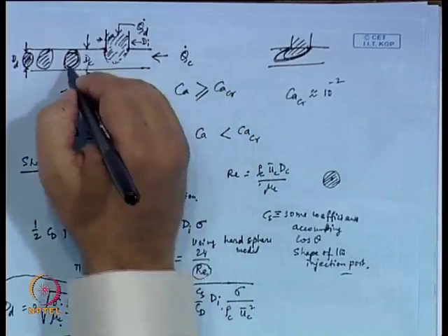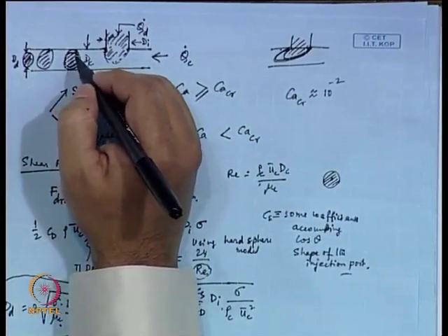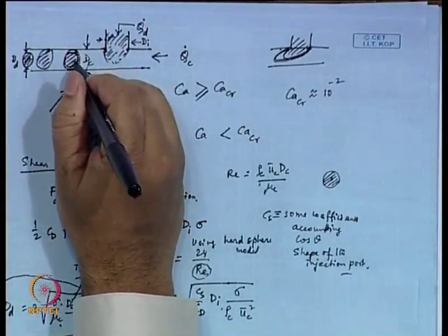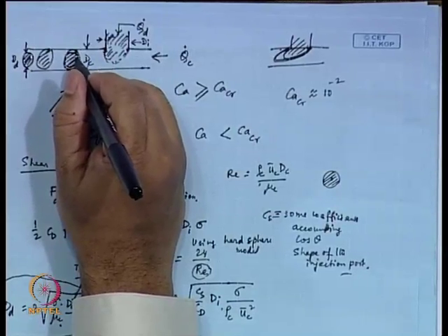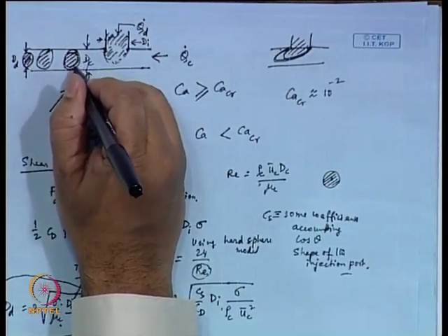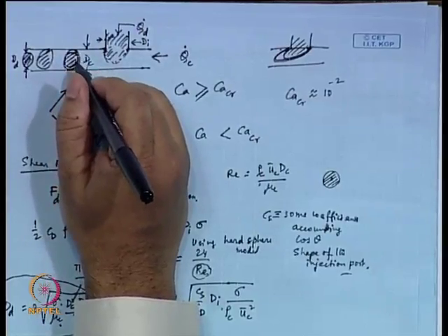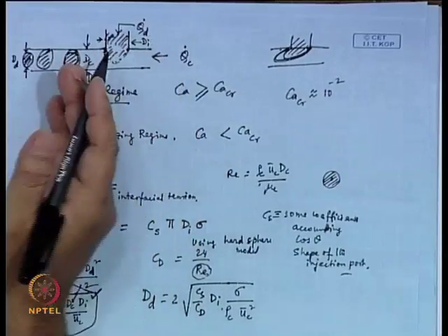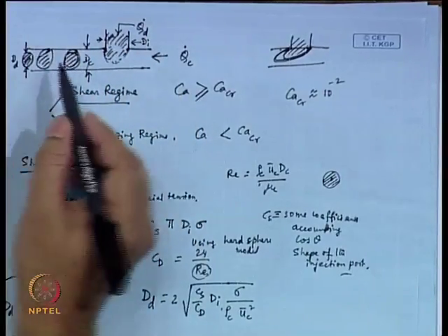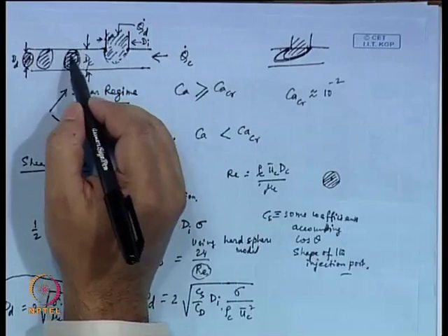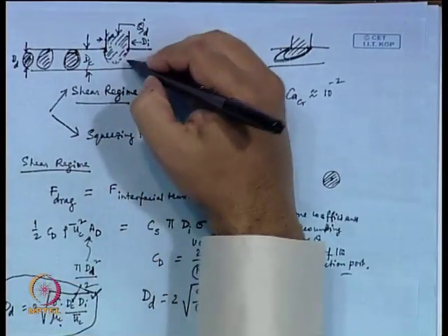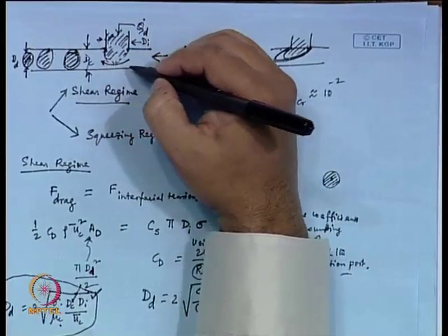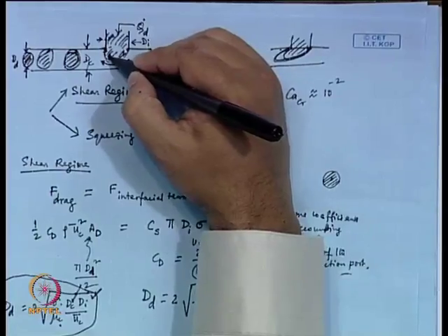After the droplet forms, there is a method called PIV, particle image velocimetry, where you can see what are the velocity vectors within this droplet. You will find that after you see an isolated droplet, there is a vortex inside the droplet, because you are producing a shear. Look at it, the carrier fluid is shearing it, right. So, within the droplet phase itself, there is a shear.